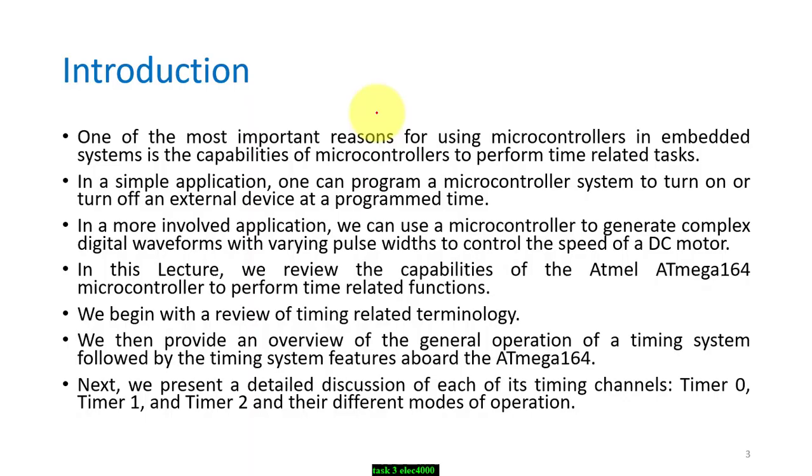Timers. Now, usually, when you want to create an output signal, we are going to use a delay signal. Delay is not good for programming, because when you put a delay signal, this means the microcontroller has nothing to do in that time. So you delay the whole work of the microcontroller. So it's not a good way to program using delays. Instead, we are going to use timers and counters.